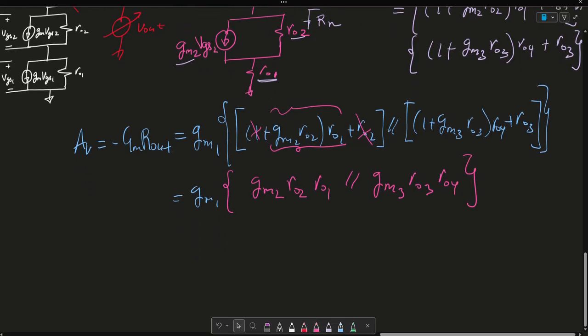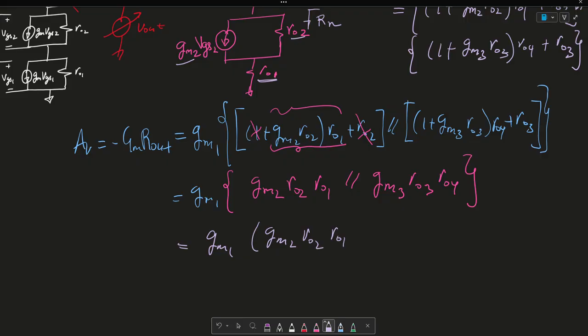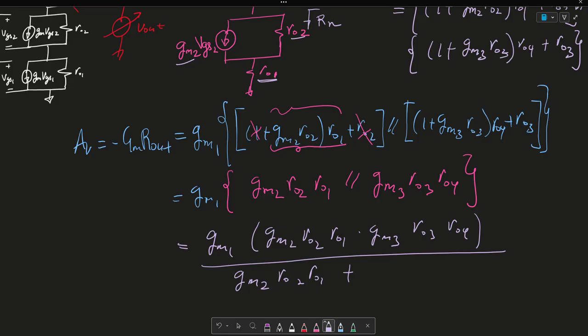Then that becomes GM1 times GM2 RO2 RO1 times GM3 RO3 RO4, over GM2 RO2 RO1 plus GM3 RO3 RO4.